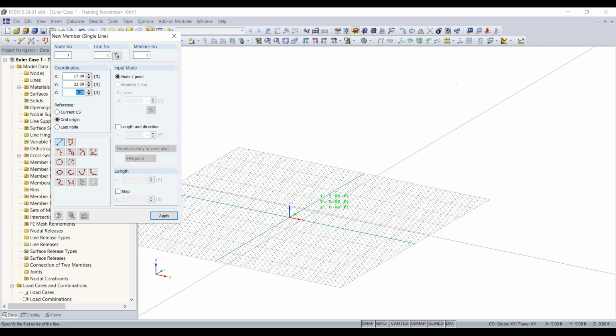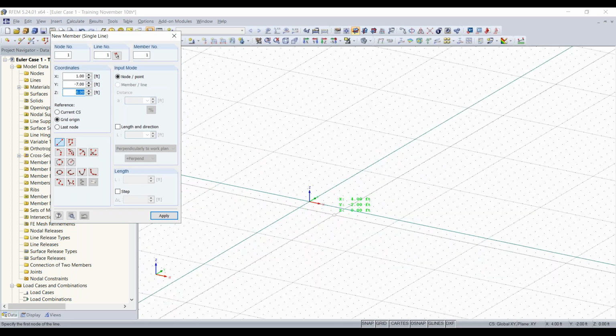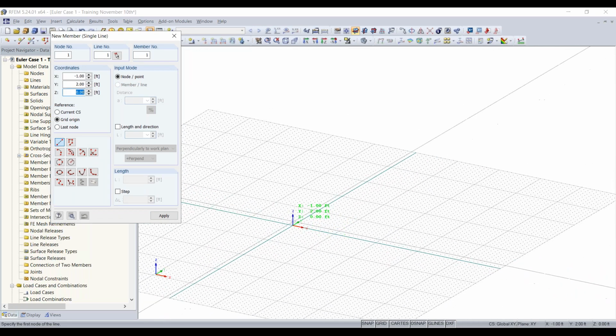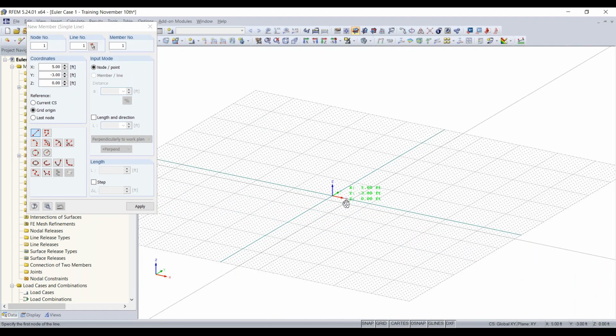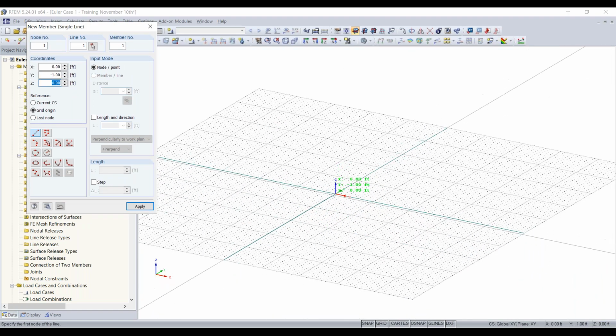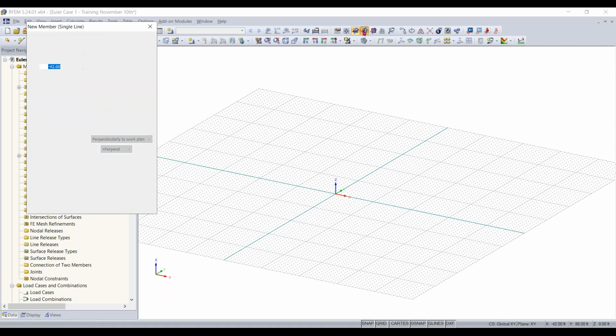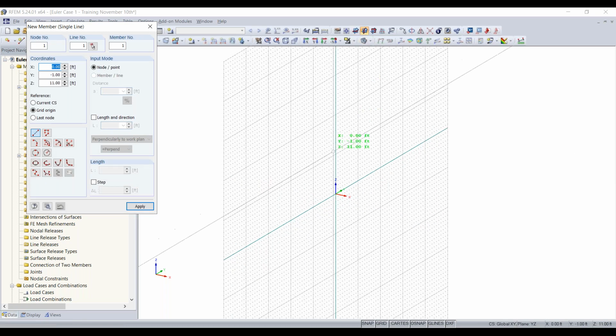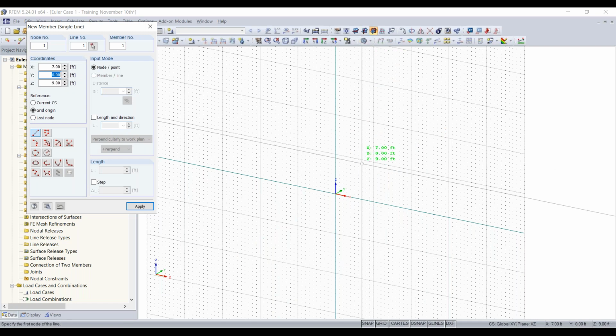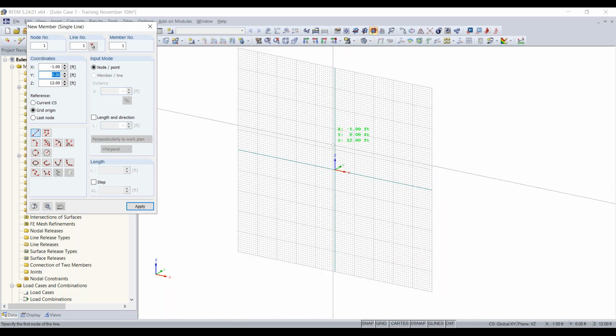And now we're going to draw our member like we did before. Let's say I wanted to draw my member perpendicular. I'm drawing a column. If I wanted to draw this member along the z-axis or perpendicular to this work plane, there are two ways to do that. I can either go up here to change my work plane from the XY work plane to the YZ work plane, or the XZ work plane, a vertical plane here.